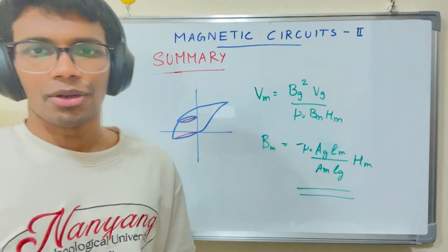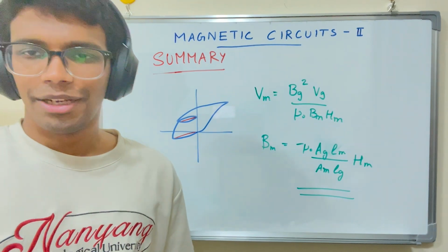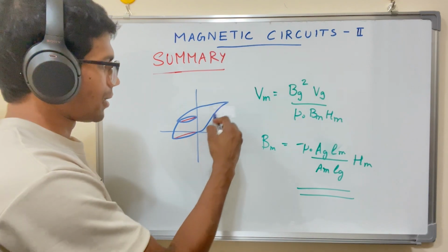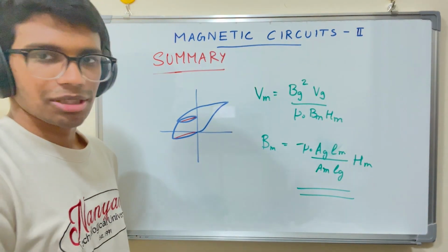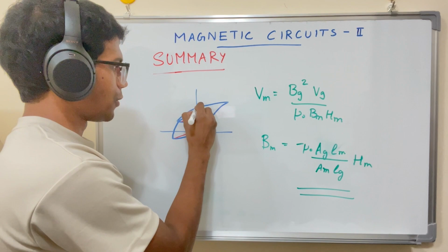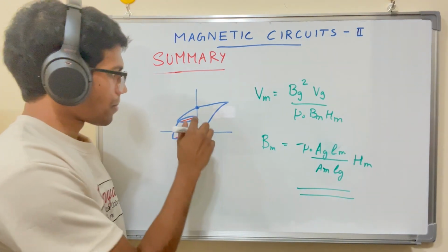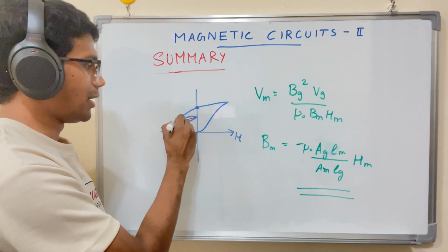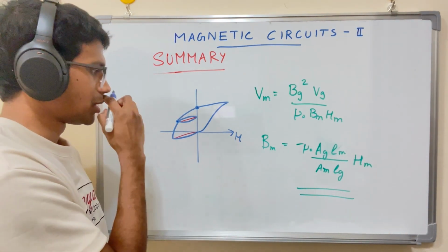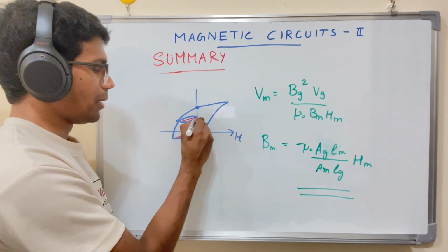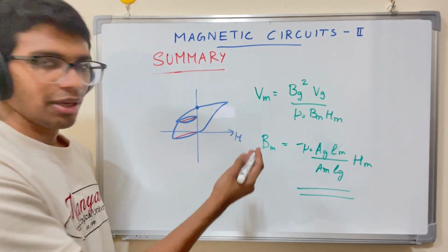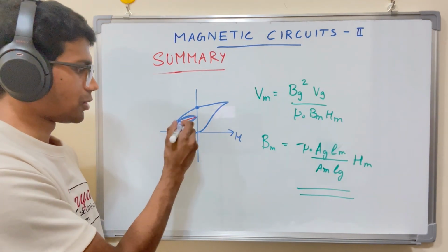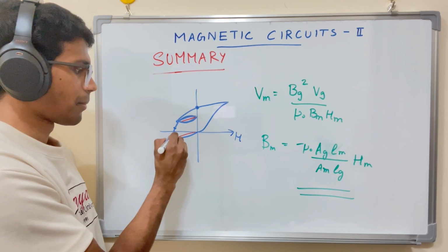Now, coming to the last part, magnetizing and demagnetizing a permanent magnet. When a permanent magnet is first magnetized and then the H is cut down to 0, this is the point of remanence. When we reduce the H or increase it in the opposite direction and then cut off the H, it follows back in a minor loop, and then when we increase the H in the opposite direction again, it goes back, and this process repeats no matter where on this curve we do it.